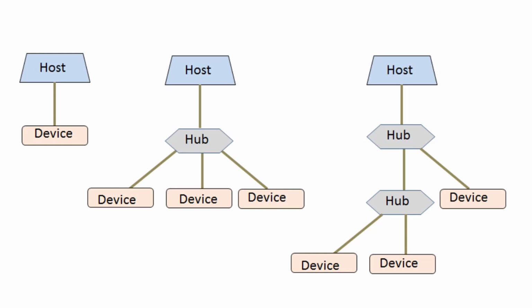If more than one device is present, we can include hubs in the tiers to expand the number of USB ports. USB hubs can extend a USB network to a maximum of 127 ports. A USB is an addressable bus line with up to 7-bit address code. This can support up to 127 devices. The address 0 is not a valid address.